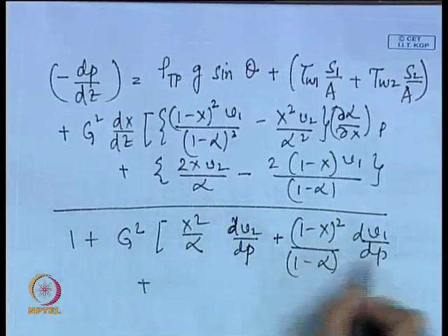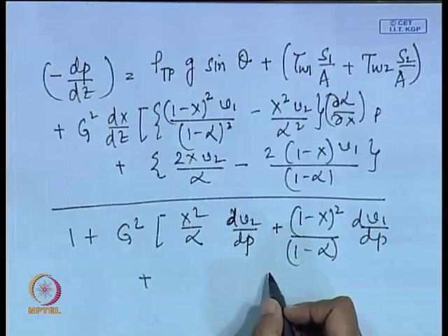And then this denominator term we compared with the compressible flow situation, and we said that in the compressible flow situation it corresponds to 1 minus Ma square, where Ma is the Mach number, which is nothing but the ratio of the velocity of flow to the velocity of sound under the same conditions of temperature and pressure as that of the flow, isn't it? So, in the homogeneous flow model this would correspond to 1 minus Ma square.